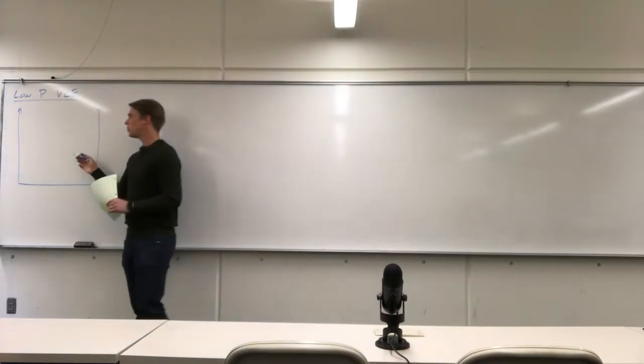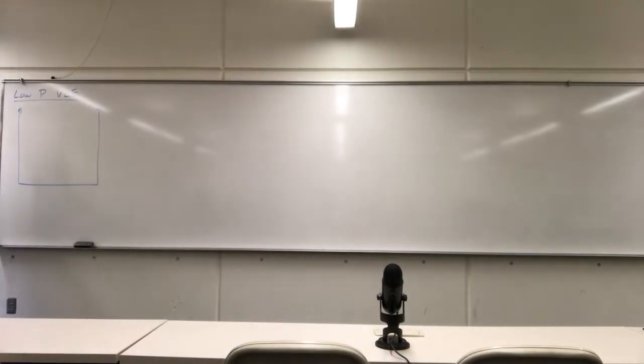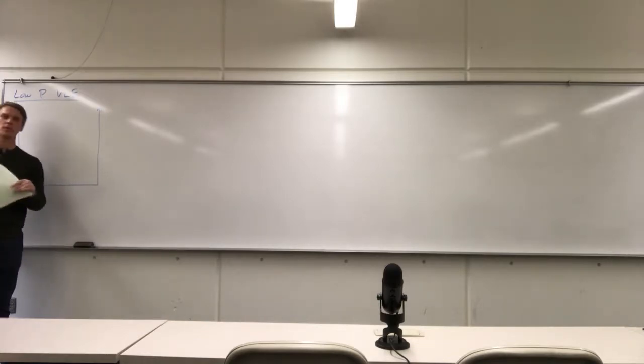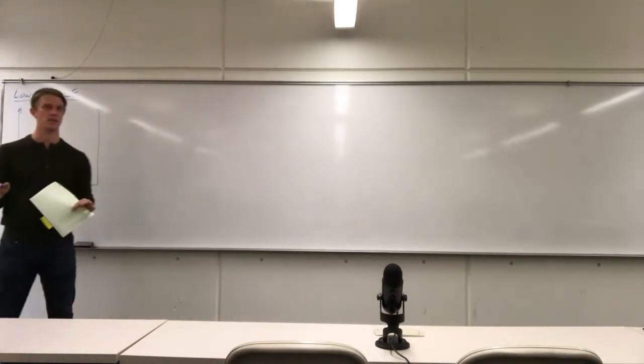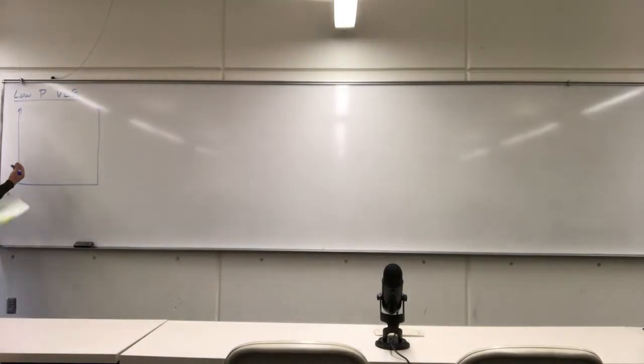So what they'll do is vapor-liquid equilibrium, fit it to parameters, repeat it as a function of temperature, and go on from there, right? But getting good activity coefficient data as a function of temperature is also kind of a pain. But just note that all the equations that we'll be doing are exactly the same. Everything's the same. It's just easier to do it from a PXY perspective.